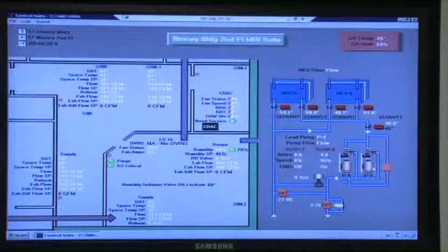And these are the pumps, P4 and P3. Here's pumps 4 and 3, so it looks like 4 is operating, and 3 is in standby. All right, differential pressures, differential valve. I'm assuming that's 0% open. That means it's not open at all. 0% bypass. So we're not bypassing, we're pumping everything down, and we're returning everything.